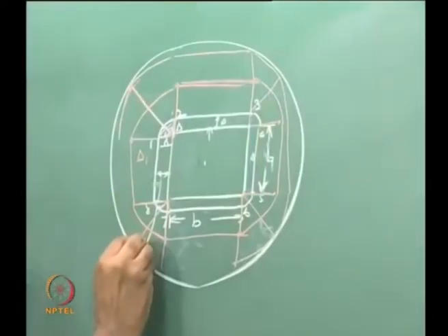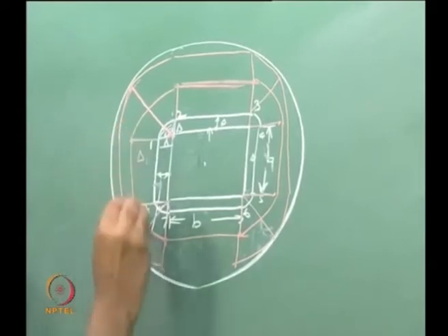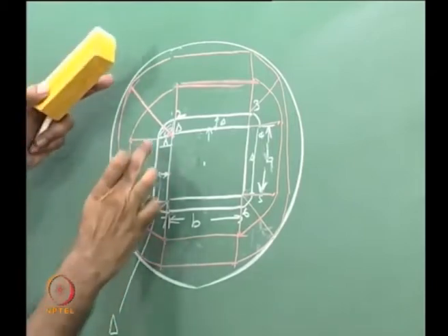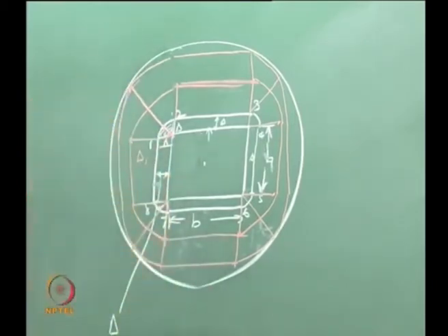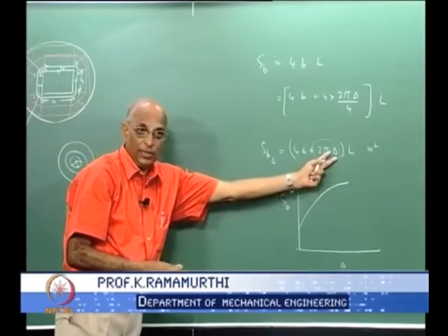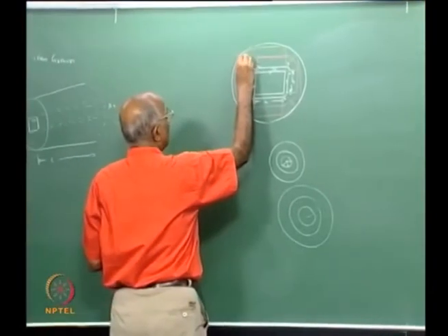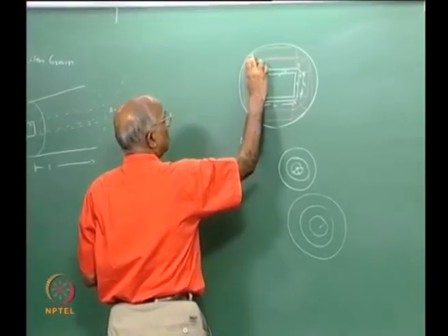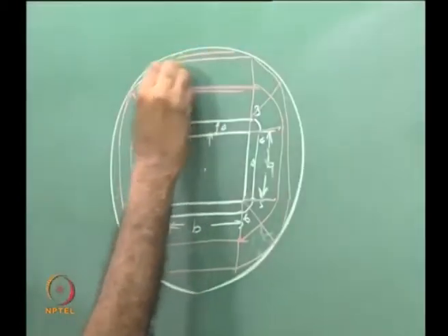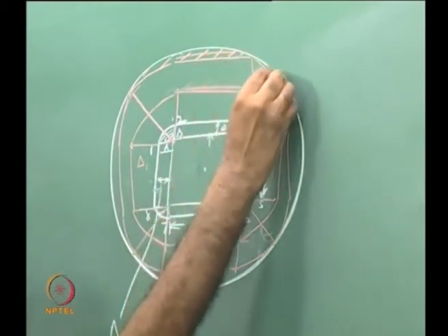Similarly, this one comes and hits over here, I have a circle like this, plane surface over here, and this is the limit. Till then the burning surface area keeps increasing in the amount 4b plus 2 pi into the gap which gets burned. Once this happens, this surface keeps decreasing because it has already reached the case, whereas this fellow continues to burn in this direction, which I now show dotted over here.